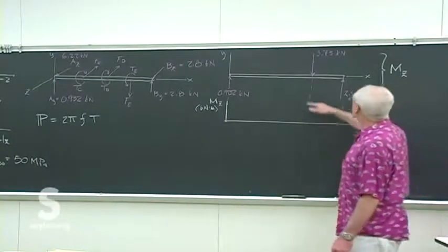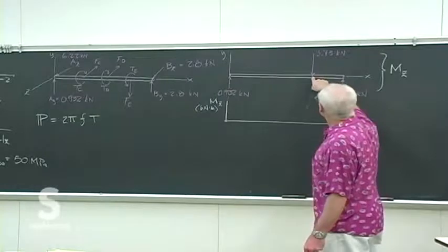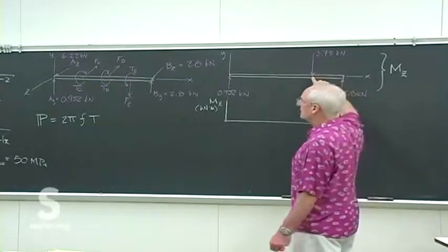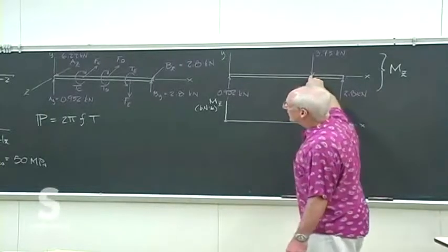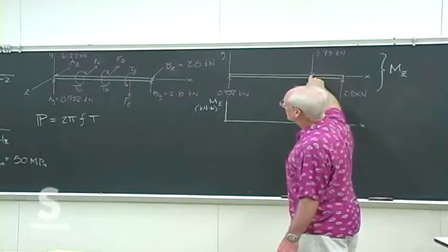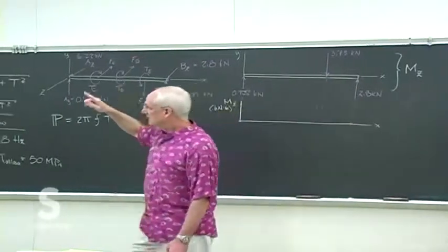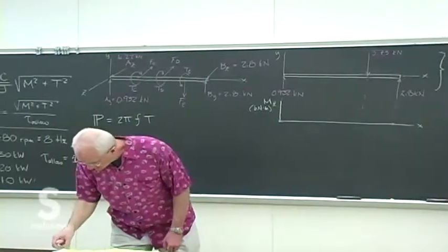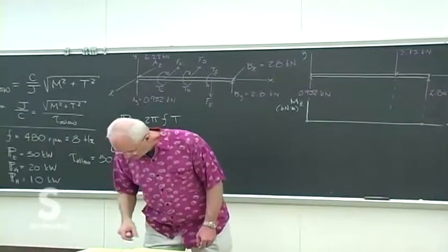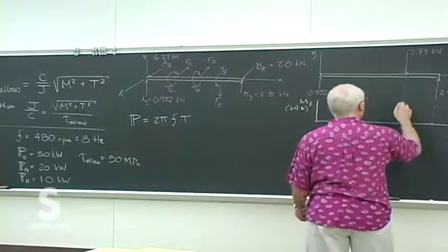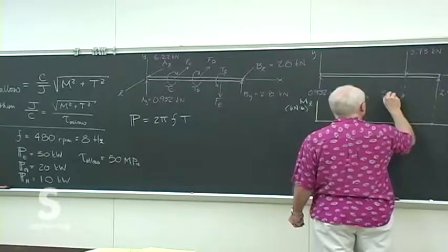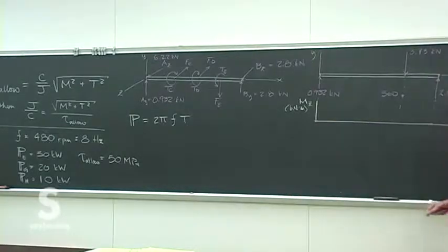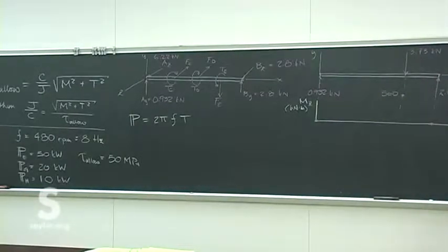And the only place we have any transverse force being applied is 3.73 kilonewtons, and that will have a moment arm all the way down of, what was it, 20.6 or something? I think when we got there. So we'll have then a maximum expected moment there of 560.